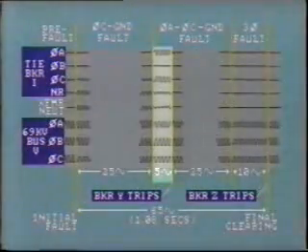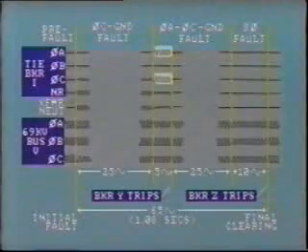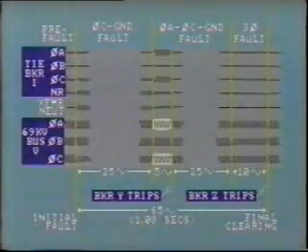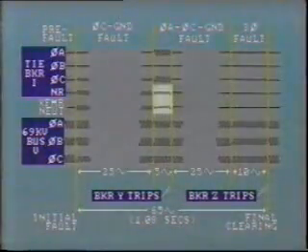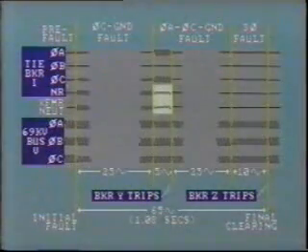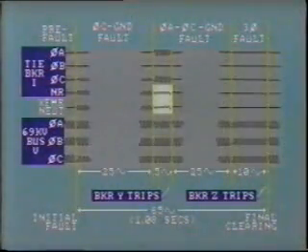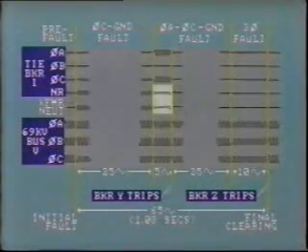At this point, the C phase conductor burns open, allowing the tree to fall onto A phase. However, the tree still maintains contact with C phase. Now, the nature of the fault has changed to a double line-to-ground fault. Over the next 5 cycles, you can see the effect of the 2-phase fault. Both A phase and C phase currents in the tie breaker rise sharply. Both A phase and C phase bus voltages are depressed. Transformer neutral current and tie breaker residual current are both still present, but they are reduced in magnitude. This is because a double line-to-ground fault is more balanced than a single line-to-ground fault.